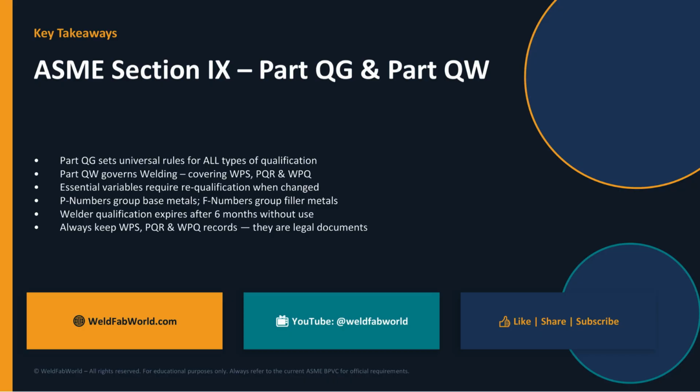1. Part QG sets the universal foundation rules for all qualification. Understand it first. 2. Part QW is where your WPS, PQR, and WPQ live. Know how they relate to each other. 3. Essential variables require requalification when changed. Always check before modifying a WPS. 4. P numbers group base metals. F numbers group filler metals. A numbers classify weld metal chemistry.